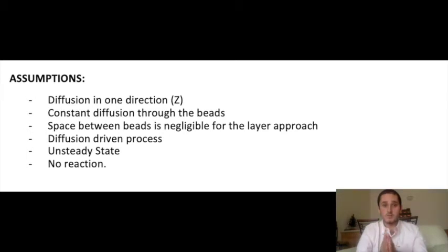In this case, it was assumed, first of all, that this is a non-steady state problem. Then, diffusion occurs only in the z-axis. Then, diffusivity remains constant all throughout the bits. And finally, there is no reaction. It is also important to mention that as bits are basically little spheres, we would be using spherical coordinates, and therefore we would need to use the unsteady state charts for spheres. Now, let's go with the resolution.